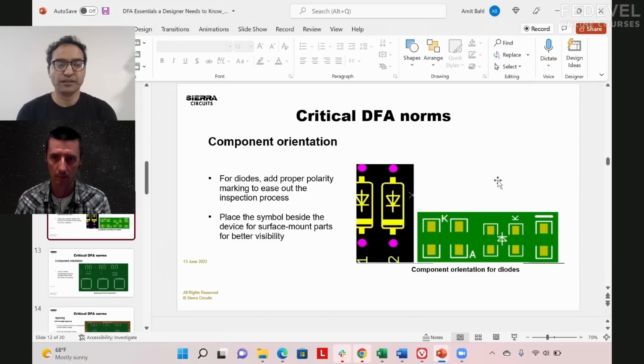If there's a component that is not good for washing, let's say it's a microphone, put that on the assembly drawing. If there's pre-tinning that needs to be done of the components, mention that as well. So assembly drawings are critical for any special process steps that are required. If there are no special process steps, then I guess the basics, right? It's a RoHS board, you need pin one, use no clean flux, like that.